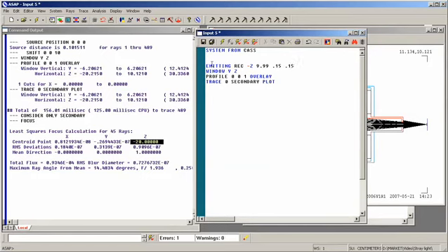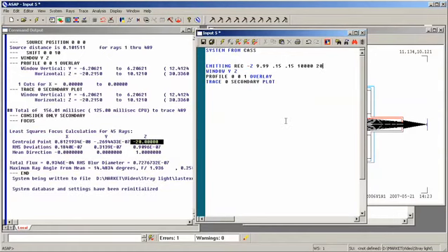That is to say the detector dimensions are 0.15 by 0.15. Same thing. And we have to tell it how many rays to trace. We'll say 10,000. And we're going to confine those rays to a 20-degree angle just to make the ray trace more efficient. We issue the end command telling ASAP I'm done with my previous work, and go ahead and execute this file.